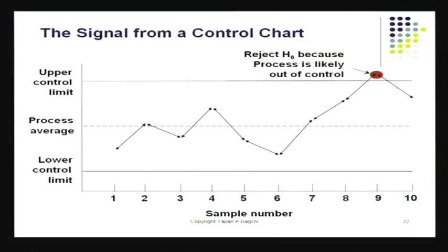Look at one chart that is shown here. It's very possible that till this point the chart was in good process control, and something exceptional happened that bumped the chart, bumped the XBar value, and it went beyond the control limit. When you go back and investigate the process, you will find a broken tool or a stopped hydraulic line, or maybe a new person came along and started fiddling with the machine, or raw material changed, or voltage fluctuated, therefore the cutting speed changed.